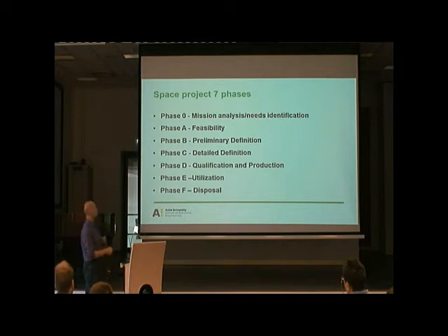Phase B, you start to define your system. Phase C, you make the real blueprints for your satellite. Everything is already tested, fitting together, working together. And then you start the production and qualification. So you make your satellite and start to qualify that it can actually work in this space environment. And then phase E, after launch, is utilization. So you use your satellite. And not to be forgotten, phase F, disposal, is more and more important nowadays as well.